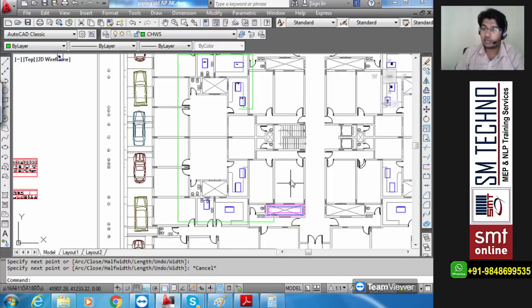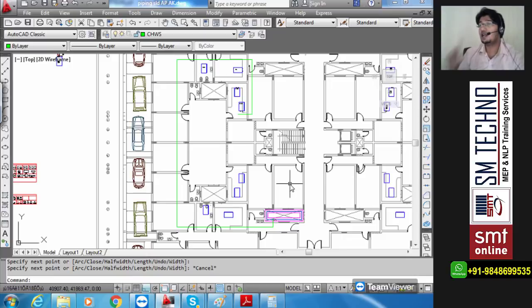Now who can tell me which level pipe? 1, 2 or 3? This is total level 1 pipe. It is starting from the chiller. Not even one AHU is connected. The moment we are connecting AHUs, which level will that turn? 2. The moment I'm connecting the return, it will become level 3.